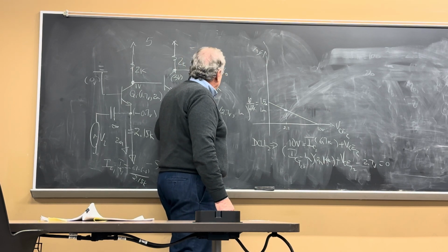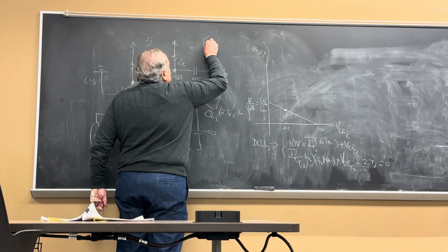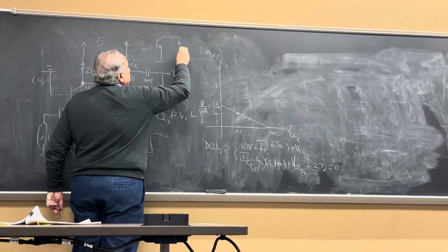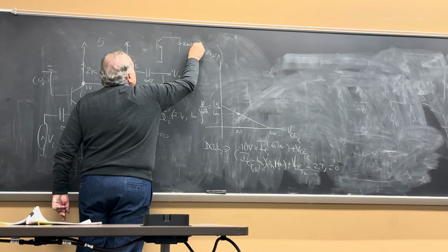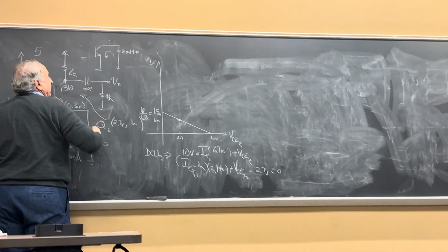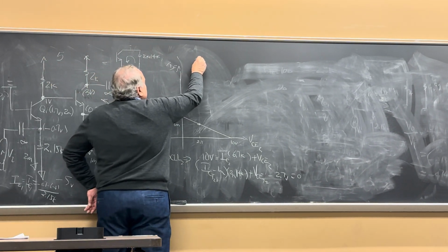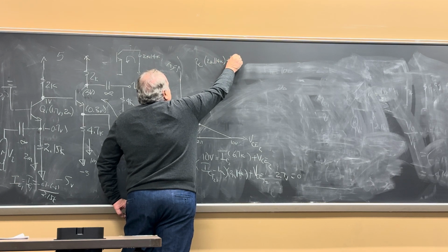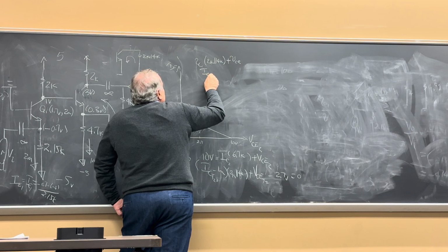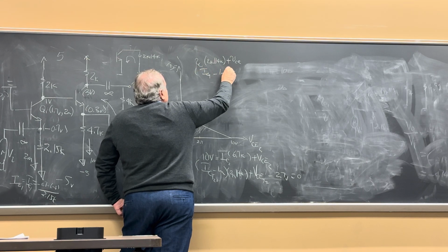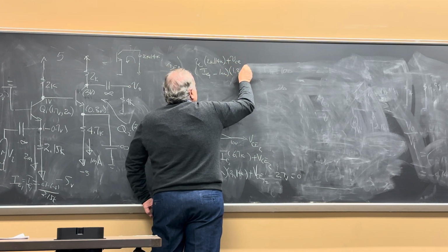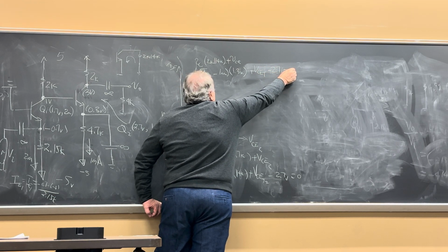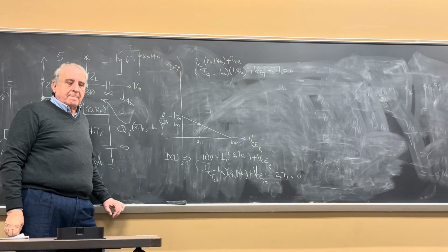Yeah. Okay, let's do the AC loop here. This is ground. This resistor is 2K in parallel with 4K. And that's a ground. Right there, you'll have I little c times 2K in parallel with 4K plus V little ce. That can be IC total minus ICQ, which is 1 milliamp. This combination is 1.3K. This will be VCE total minus VCEQ, 2.7 volt. Okay? That's that.